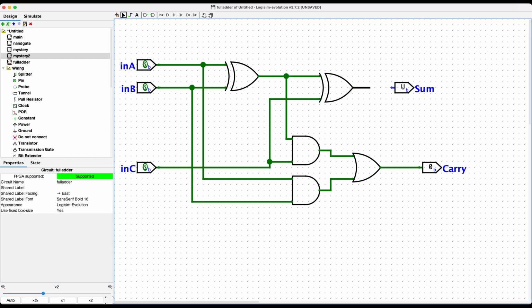Okay, so right now, what are all 3 of my inputs? They're all zeros, okay? So what should I generate as my sum and my carry in that case? Well, clearly all zeros, right? Okay, so let's change it to the situation I had up on the board, which was one of the inputs was a 1, the other was a 0, and I had a previous carry. Okay, what's the sum in that case? A 0 with a carry.